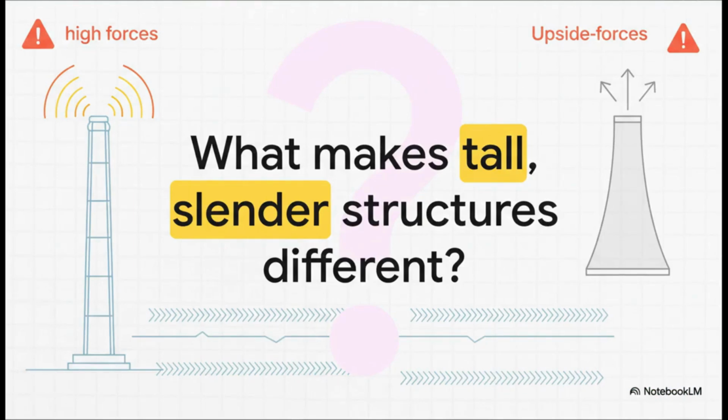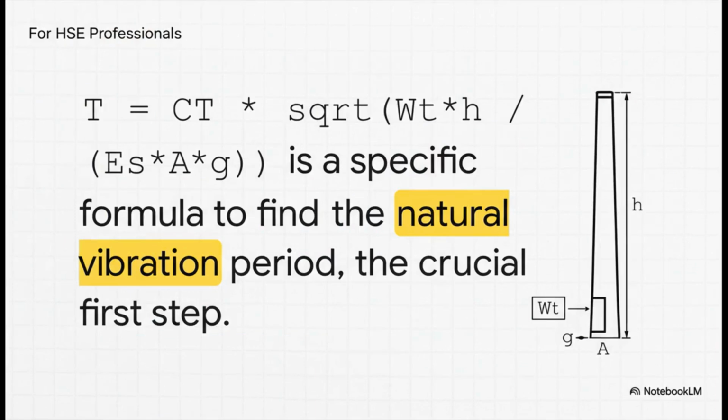Well, in engineering terms, they act like giant cantilevers. Imagine a diving board fixed at one end. When the ground shakes, you get this whipping effect, where the very top of the structure moves way more violently than the base. This can create absolutely incredible forces at the top, so the standard has a very specific way of dealing with them. And it all starts with getting the time period right.